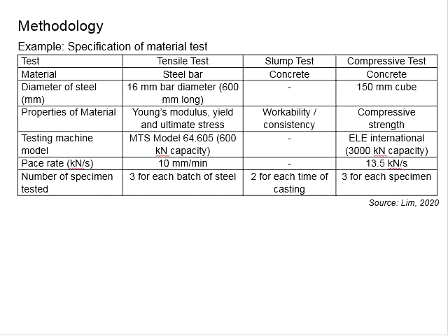And then you have to be careful about the standards that you are using in the later stage of your analysis, whether you are following the Eurocode or British Standard. The concrete strength as specified in the British Standard is on the basis of the cube, and the concrete grade as specified in the Eurocode equations is on the basis of the cylinder.